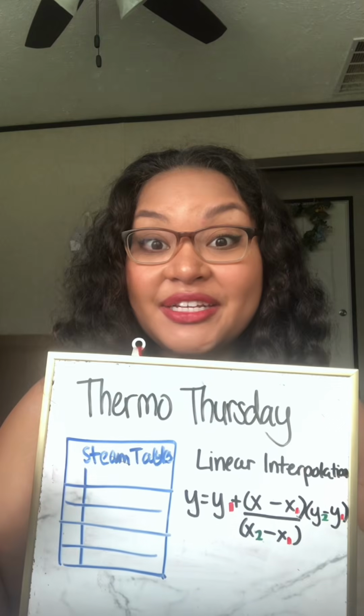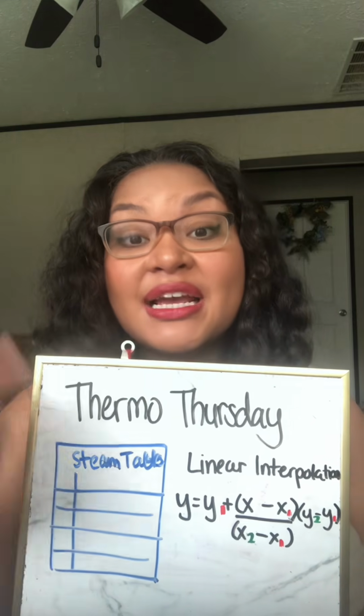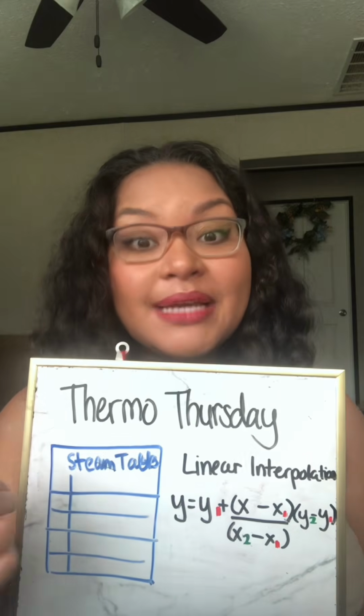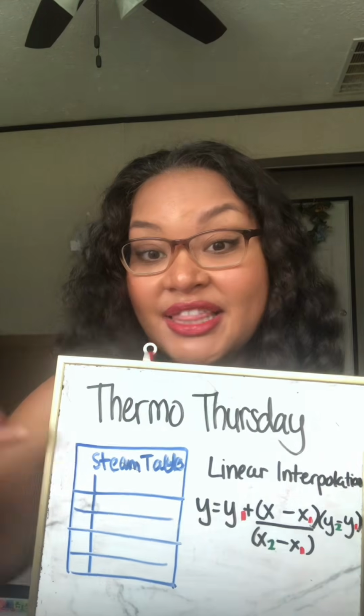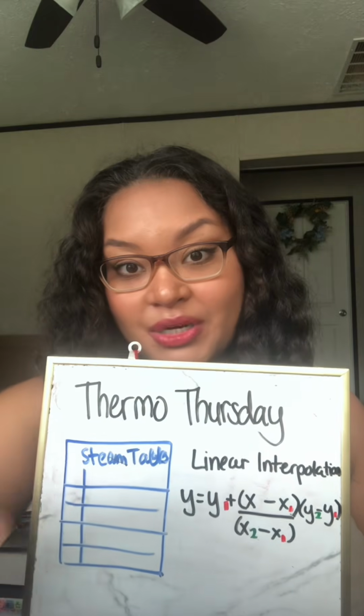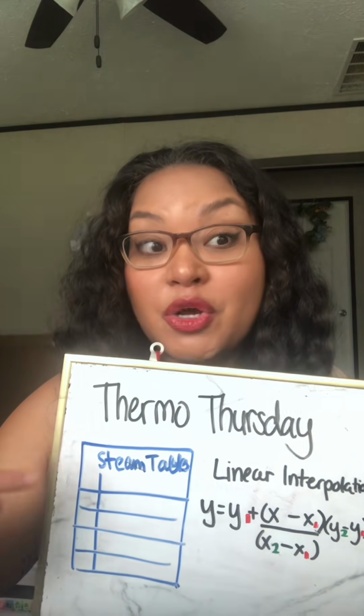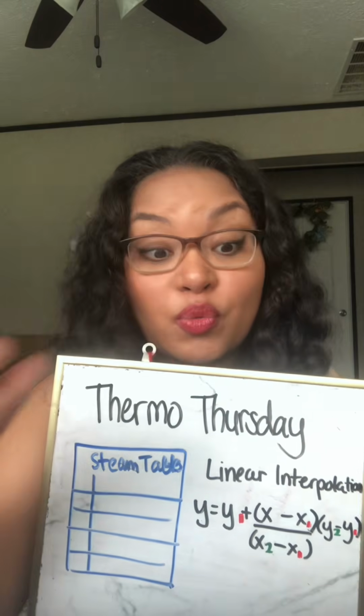Another thing you're gonna get used to is the thermodynamic tables, but you'll typically be started out with steam tables, and a tool that you need with steam tables is linear interpolation. This does the heavy work, and then this helps you to get even closer to the point that you want. Steam tables are typically in the back of your textbook, so make sure that you know how to find what you're looking for when you're reading a problem.